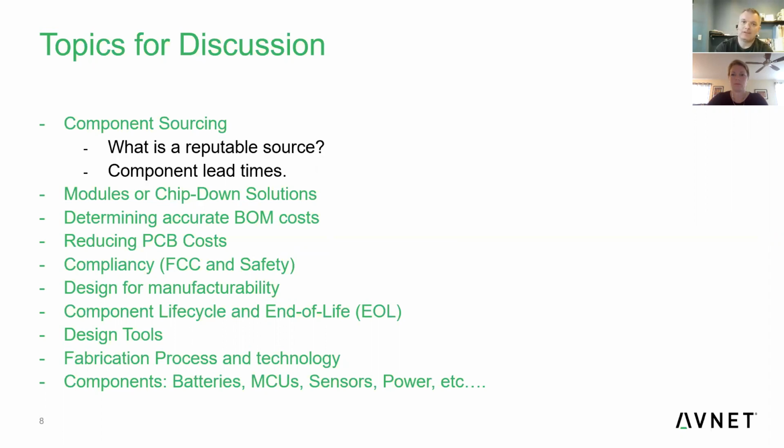Using a module can still save you a significant amount of time and effort. When you use a module, the modules are typically pre-certified, which means they've already gone through FCC testing, especially around how it radiates as a module. When you integrate it in your product, you still have to get it tested, but the testing is significantly different.